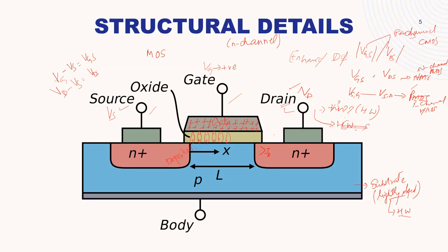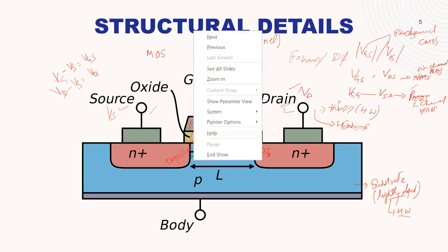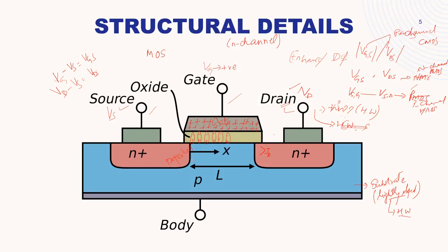Now, what will happen? Between the dielectric and the substrate boundary, charges will start getting attracted to this plus at the interface. So from here, electrons will start flowing upwards from the P substrate. And in the P substrate, my electrons are minority carriers.